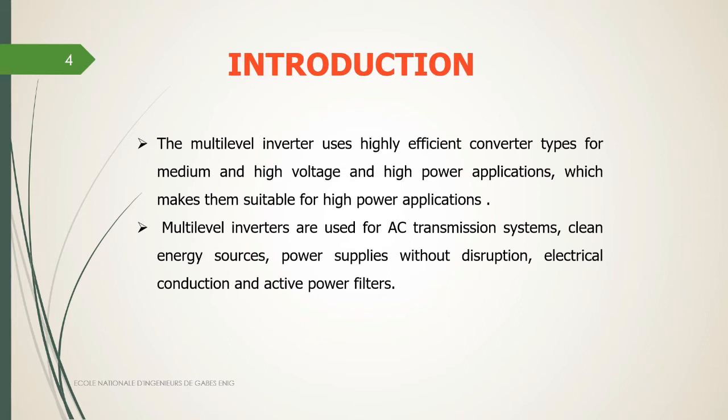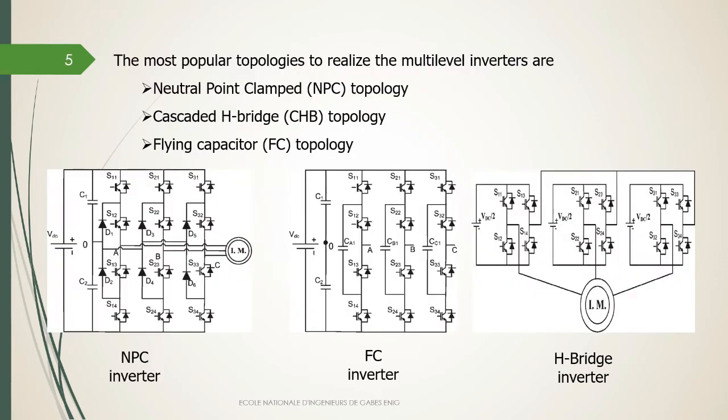For the 5-level, the most commonly used topology is the neutral point clamped NPC. In neutral point clamped inverters, the DC link is split into many small voltage levels using a series bank of connected capacitors. A 3-phase 5-level diode clamped inverter is shown in the picture.